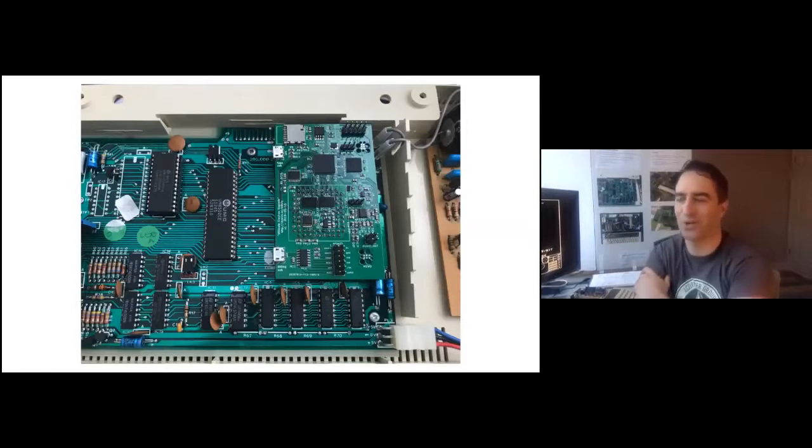And then I checked all the pins one by one. I had basically a resistor connected to a wire which plugged into either power or ground, and I would touch it to each of the pins one by one, and then run a debug command through the microcontroller in the FPGA, which would read out what it thought the pins were. Everything worked. So that was a small miracle.